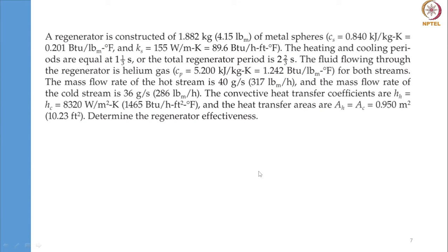So the NTU of this heat exchanger comes out to be 21.11. So we found that as UA by m dot Cp min. M dot Cp is straightforward, m dot Cp of cold fluid. So we found out UA as (1 by hA of hot plus 1 by hA of cold) raised to the power minus 1. So NTU is 21.11. Next up, we are going to find out